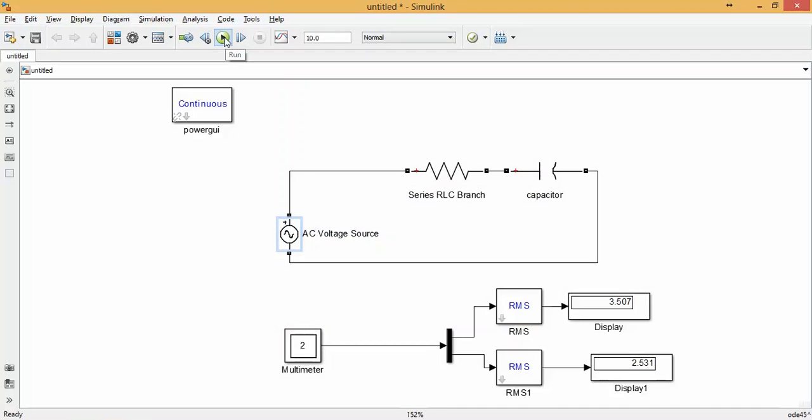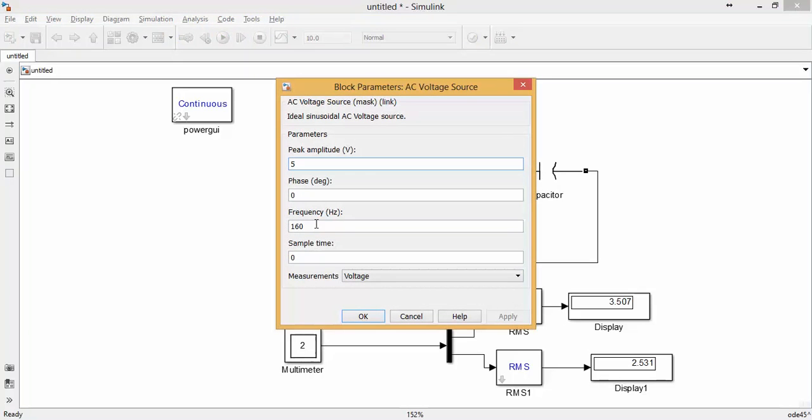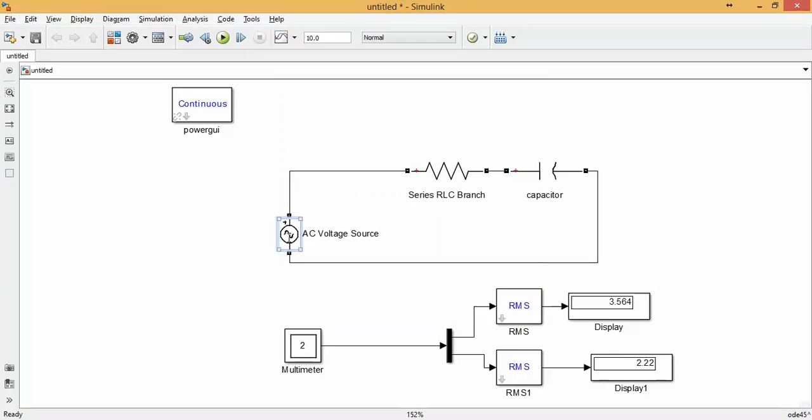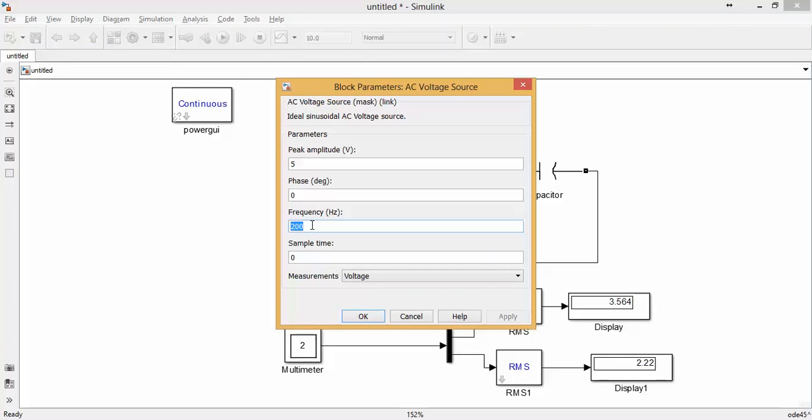The output is reducing. And as we know, there is difference between ideal filter and practical filter. That's why this frequency is not reduced abruptly. This is reducing with a slant. So next we are going to change it to 200, and we'll do it until we are getting value almost 0 or near to 0.